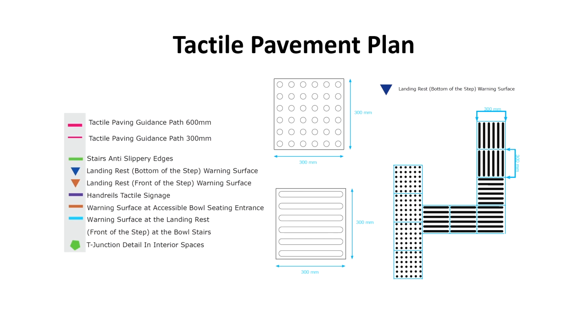Once the location is determined, we move on to selecting the appropriate type of tactile paving for each area, like warning paving, which alerts individuals to a potential hazard like a staircase. So they have to be careful, they become conscious of it because there is a level difference. The design typically includes raised bumps or bars arranged in a specific manner.